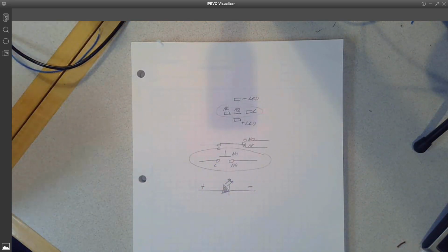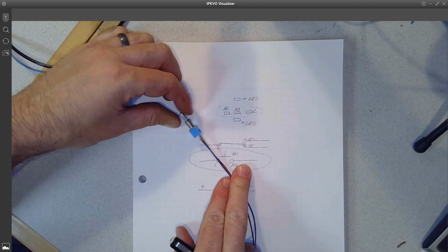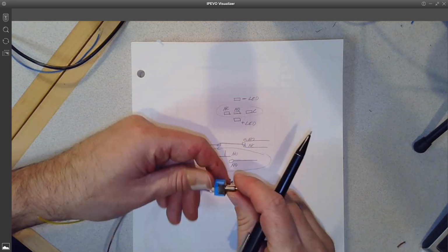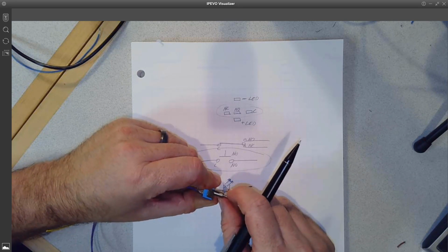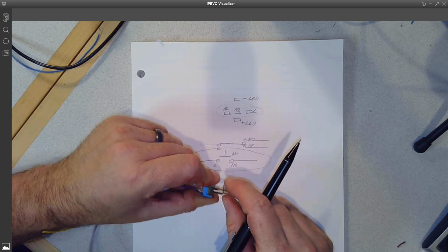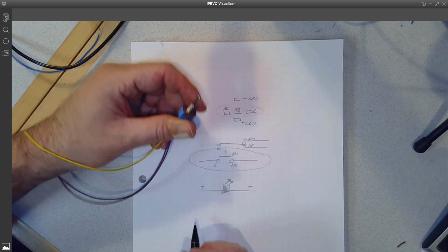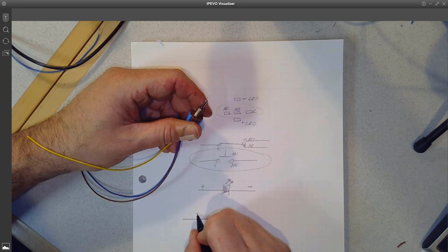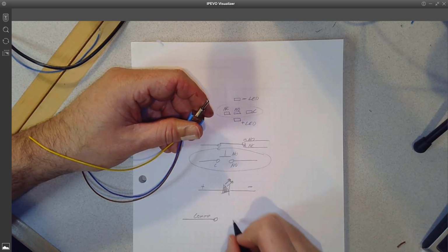Then let's look. The other one we're going to work on is the toggle switch. So this one, the schematic would be more like what we showed up here. It's a 3-position toggle. So you can represent either up and down as 2 separate switches, which is probably what I would do. We could do it different ways, but I would probably represent it like this, with this being the common, and then having 2 different positions.